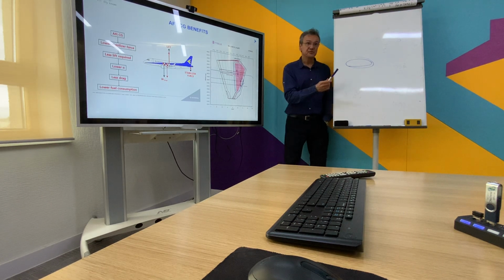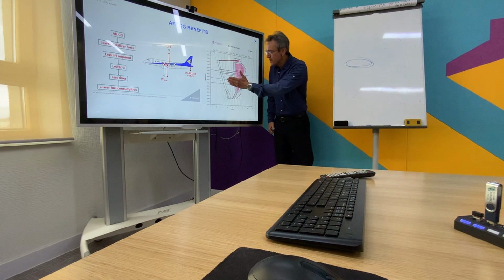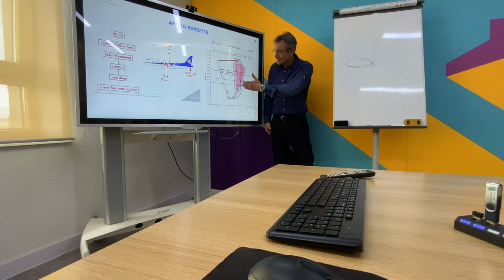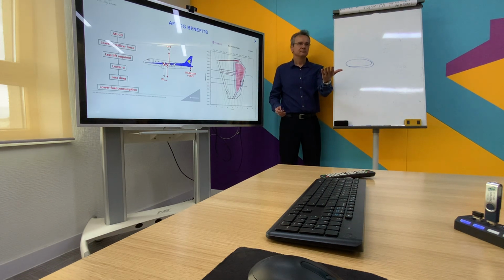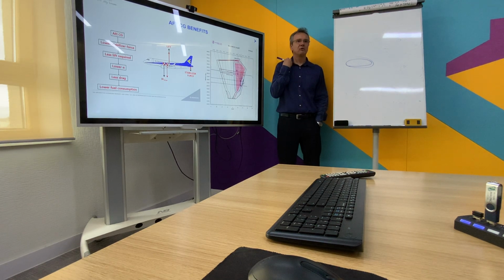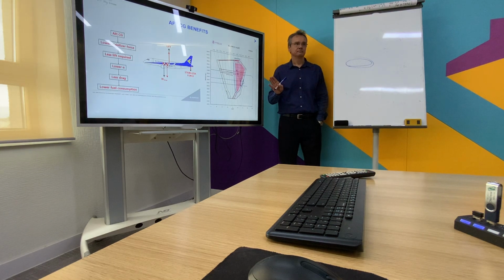The alternate CG was to increase the payload. Bringing the takeoff CG and zero fuel CG as aft as possible is only to save fuel, to offload the elevator force that counteracts the lift and lower the fuel consumption. It works for the E2 and for the E1 as well. It's the same rationale. If you do it this way, you are saving fuel. Always.